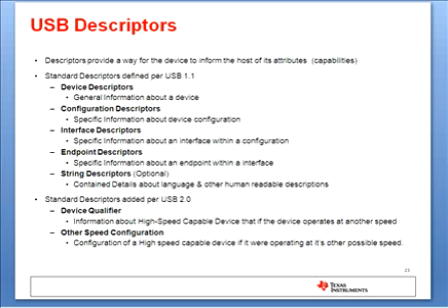USB 2.0 appended 2 additional descriptors. When utilizing the high-speed throughput of the USB 2.0 bus, 2 additional descriptors are needed. The first being the device qualifier, and the second being the other speed configuration. The format of all these different descriptors can be found in Chapter 9 of the respective USB standard. For the sake of time, I will refer the reader to Chapter 9 of the USB spec for a detailed description of all the descriptors.